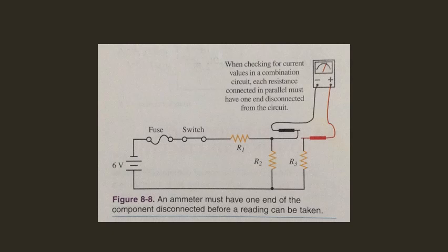Look at figure 8-8. Current readings are an excellent way to determine if the circuit components are operating correctly. But this method should be used only as a last resort if it involves desoldering the circuit to take readings on individual components. Total resistance can help determine if a circuit is operating correctly, but care must be taken to avoid a false reading caused by reading a component in parallel with another component.